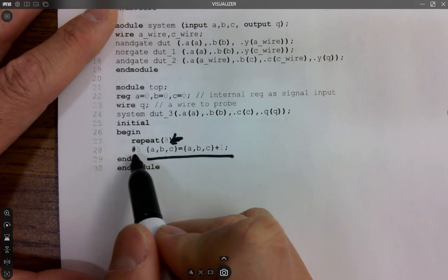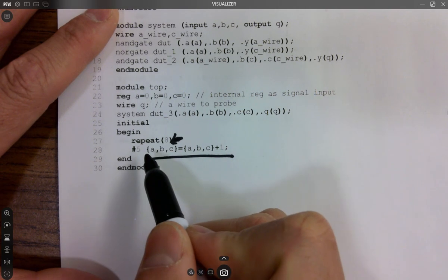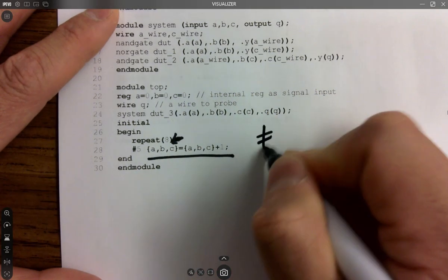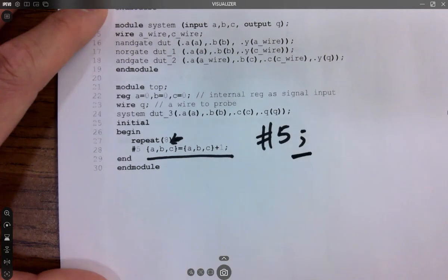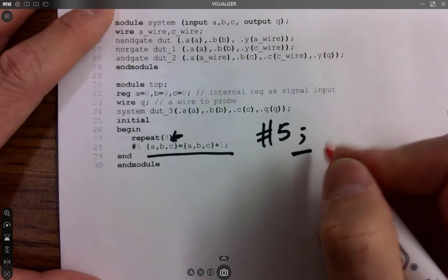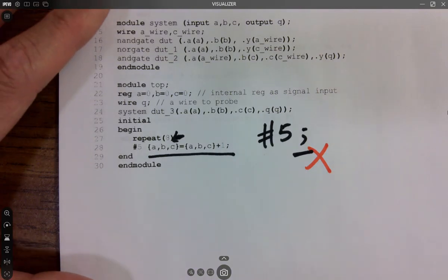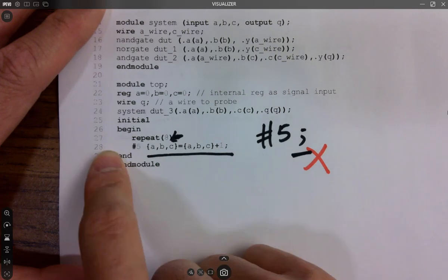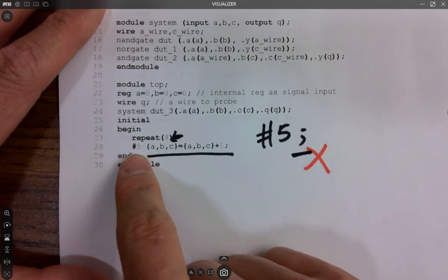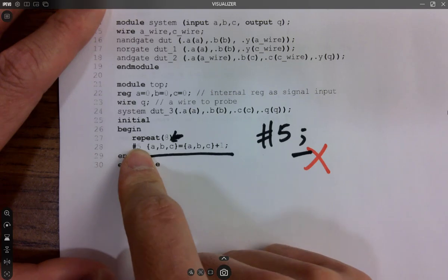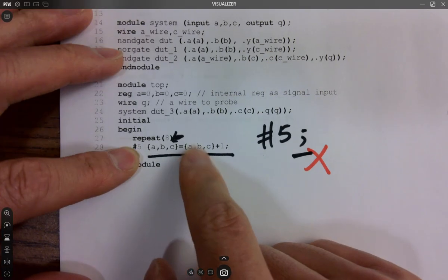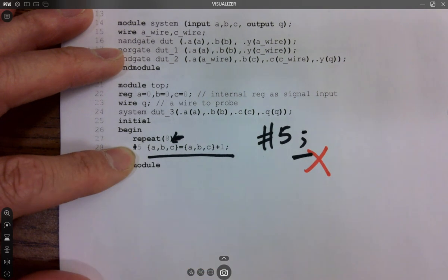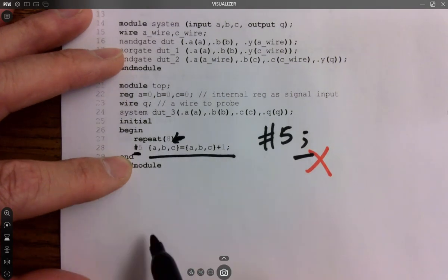Another problem I found was you see a constant value after the time delay without any changes. It's because you have a semicolon here right after the time delay, which is wrong. And eventually it's not making any changes. So the goal is making the whole thing in this line one statement. So right after this time delay, it is able to add a point to it. And this is an extension to the previous value. You know what I mean? So this one is the delay of the previous value.